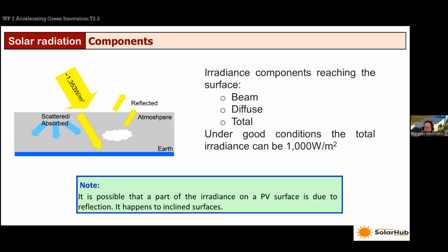Thank you so much for allowing me the question. When the manufacturers talk about, or when we are doing the testing of, solar panel efficiency, it is done by a solar sun simulator, the Spire sun simulator, and there they calculate only the direct sunlight, which is perpendicular, 90 degrees to the panel. But in the real case, you have diffuse light, and that should be measured.